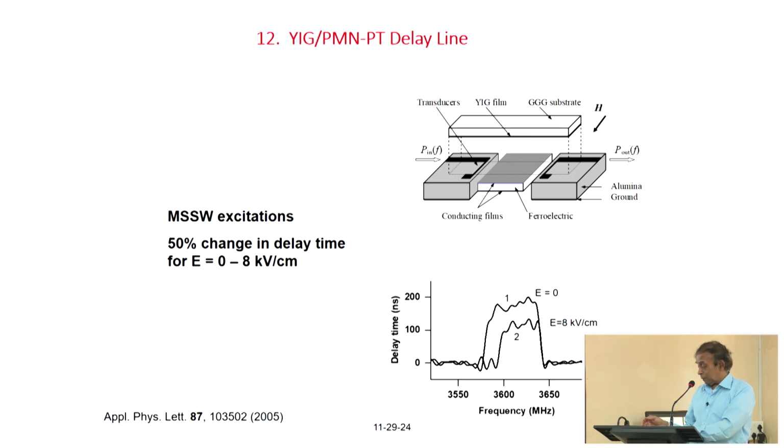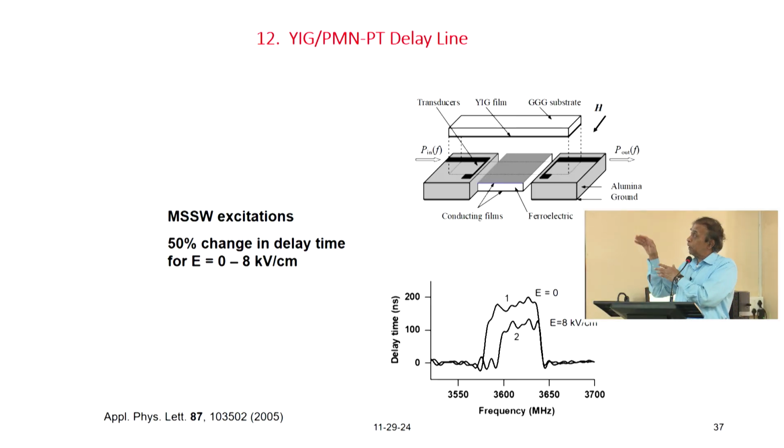So, what is a delay line? When at the receiving end of a radar, you have microwaves coming in. So, you can have the resonator pick those frequency band, but ultimately you want to have the selectivity for a particular frequency. So, that is where the delay lines come in. As the waves come in and propagate through the YIG, you can separate them in time domain using this delay line. So, it will convert the signal from the frequency domain into time domain, so that it will be received at certain time intervals, and that is what is shown here, the time delay over a certain frequency range.